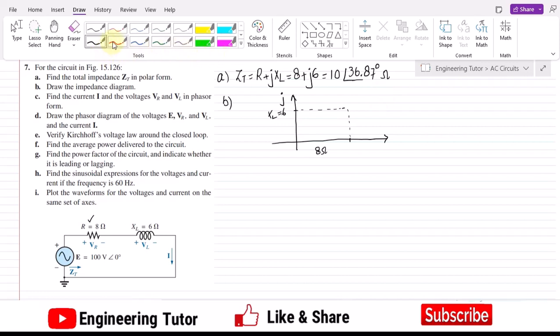Let me use this blue color. This is the 8 ohm resistor, this is the XL, so now the resultant is this, and this is Zt, and the value of Zt is 10 ohm, while the angle it makes with it is 36.87 degrees. Okay, so that is the impedance diagram.